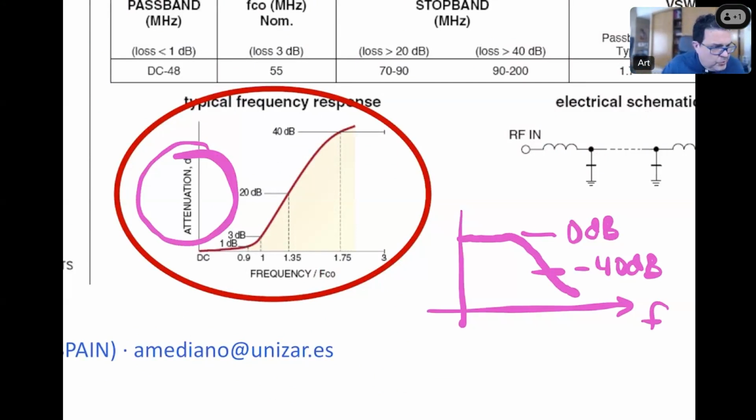So let's switch to the camera so you can see the Bode 450. Okay, so I have port number 1, I have port number 2, I have 2 coax cables, and at the end of these coax cables is where I will be connecting the filter. But before connecting the filter, we need to make the calibration of the system. Calibration means that we will be able to translate the reference planes from the input port of the instrument to the end of the coax cables.